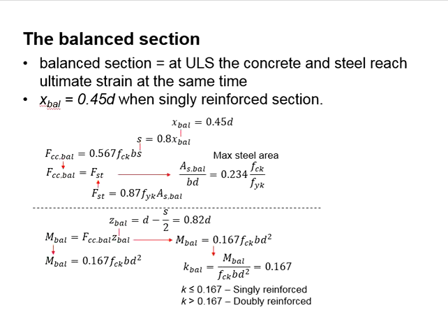Now you know how Eurocodes prevent the members from being over reinforced. In the design of reinforced concrete beams, there will always be a step checking for the maximum steel area in the member. If the amount of reinforcement exceeds that, you will have to redesign the section. You cannot use the section because it will be over reinforced and ductile behavior cannot be ensured.